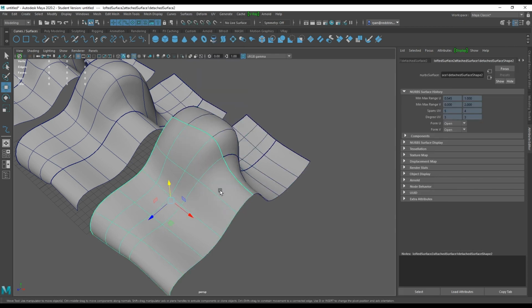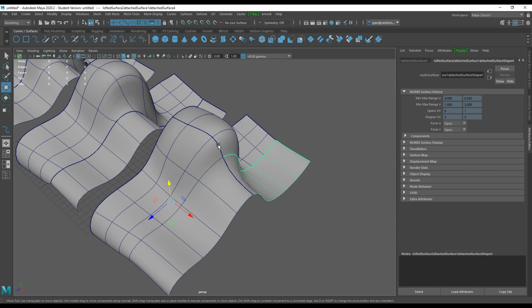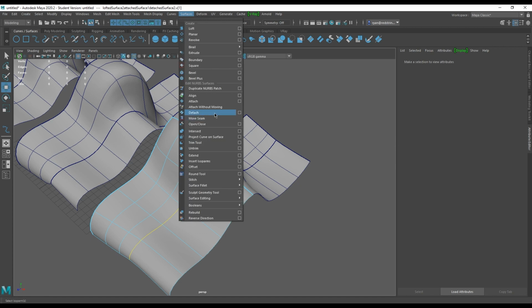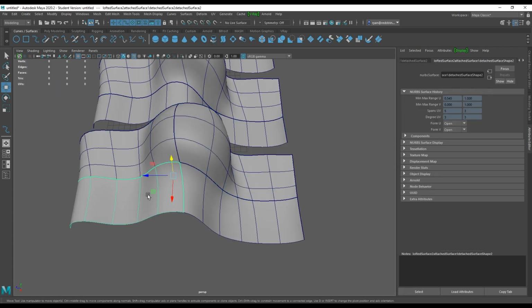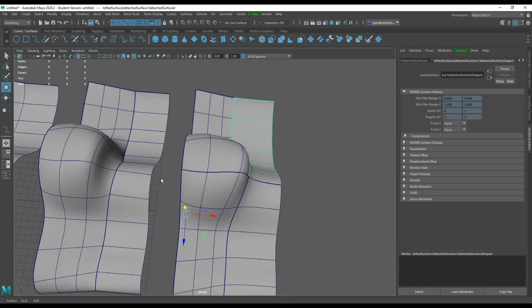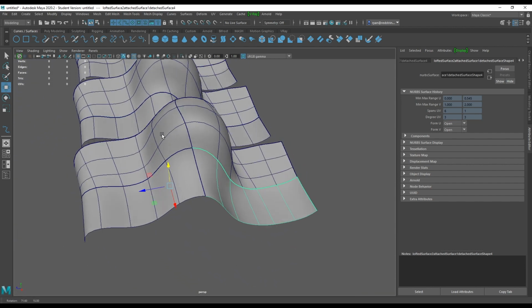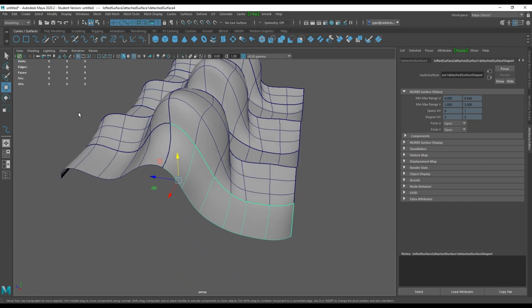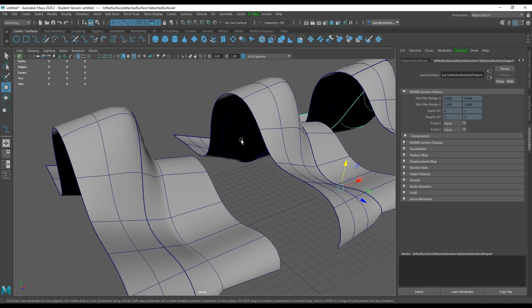And now you'll see, we have three because this one detached before this one could detach. So again, just go to isoparm, do that, surfaces and detach. Now we've got 4 different NURBS surfaces from the original one that we now can use to either produce more different curves or whatever our hearts desire.